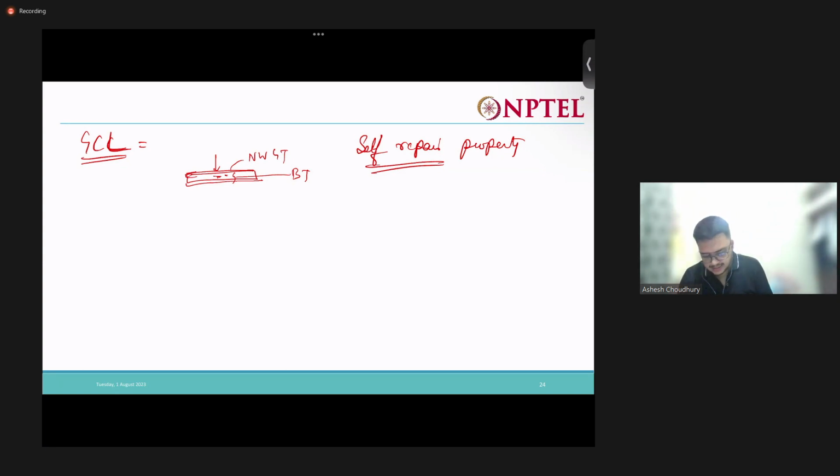Okay, next we have geocell. Geocells, as we already discussed, we saw the image also of geocells, right? These are mostly hexagonal, box kind of things. Whenever we fill the geocells with soil, whenever there is load on that soil, inside the geocell there is a confining effect.